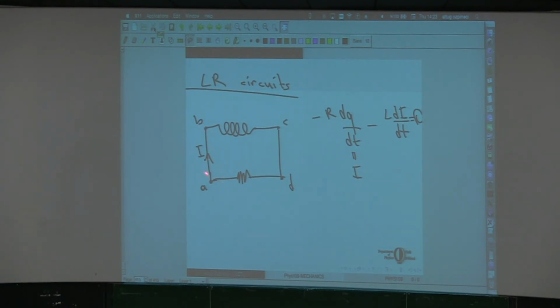Because if the current is running, you are dissipating energy. If you are dissipating energy, where does that energy come from? It is nothing but the energy stored in your inductor. As long as there's a current, there's a magnetic field inside your inductor which holds the energy. It will be giving you the energy that you dissipate through the resistor.